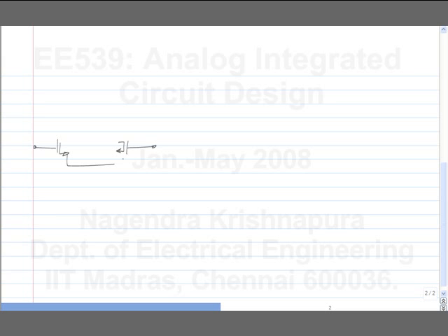So a common gate amplifier, we know, works as a current buffer, and that's what we want here, because we have this differential pair. If I apply a differential voltage to it, I get some current variation around the bias value. Okay. Now what is a common gate amplifier?